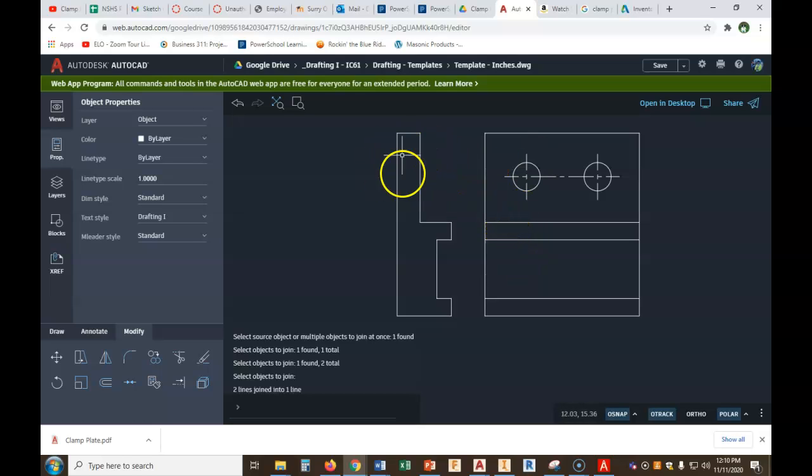Those holes are here in this object. We just can't see them. So what do we do? We draw the hidden lines. Remember the hidden lines? I'm going to go to Draw. I'm going to leave it. I've got my properties on. I'm going to leave my layer as object. That's fine. We can change it if we wanted to, but let's click.